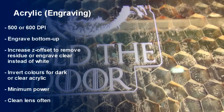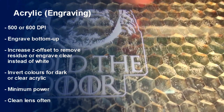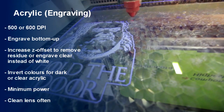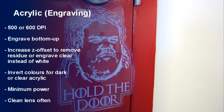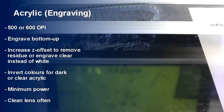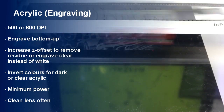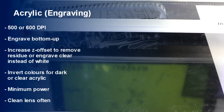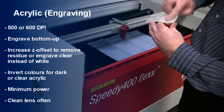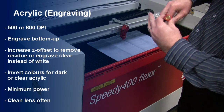Tips for engraving on acrylic. You want to use 500 to 600 dpi. Your engraving direction should start from bottom up. Increase the Z offset to clean any of the residue or engrave clear for clear acrylic. On clear or dark acrylic, invert your colors for a better contrast engraving. When engraving, you want to use minimum power to etch the surface without creating excessive residue. If engraving acrylic often, please keep in mind that you may want to clean your lens or machine more often.